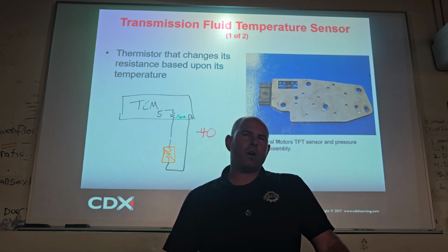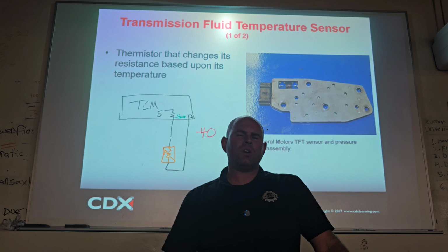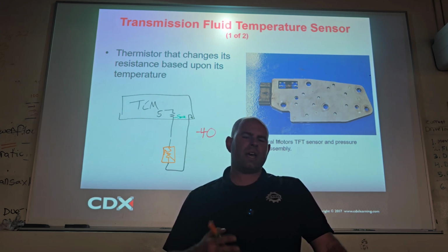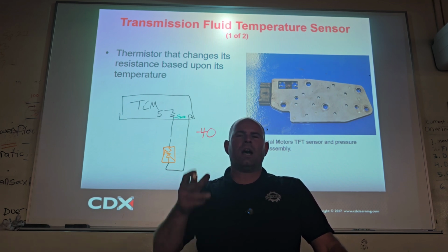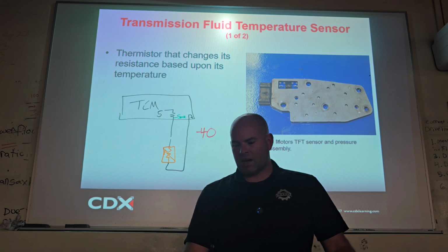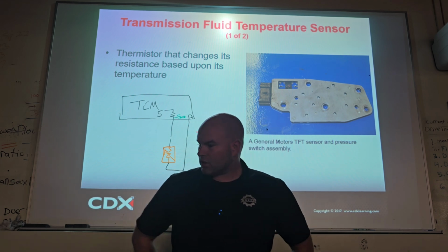If it's a pretty new car and we're feeling like we want to go in there, I think if you explained, hey, I measured it, I know that it's an open circuit in the transmission fluid temperature sensor, I want to drain the fluid, I want to pull the pan, I want to fix the sensor, which by the way, I was carrying this harness around just for this.